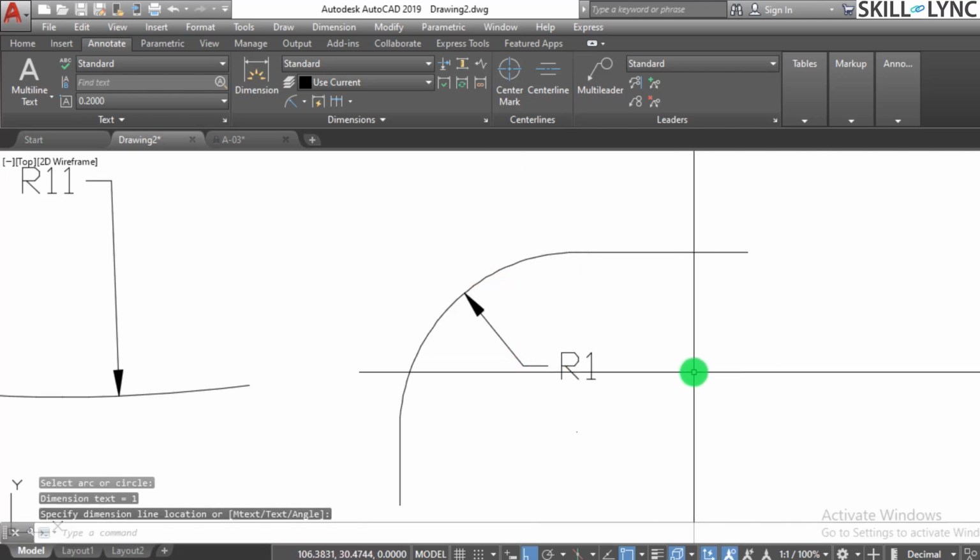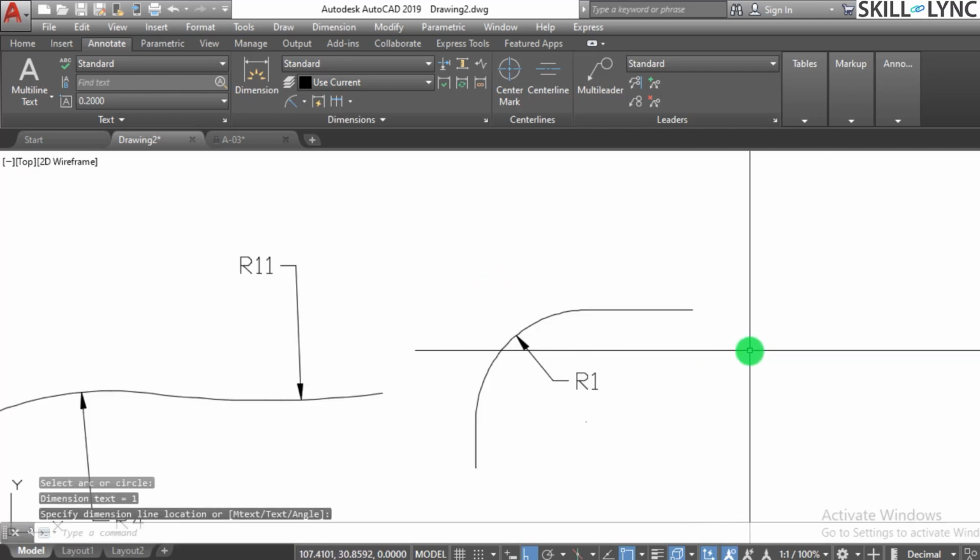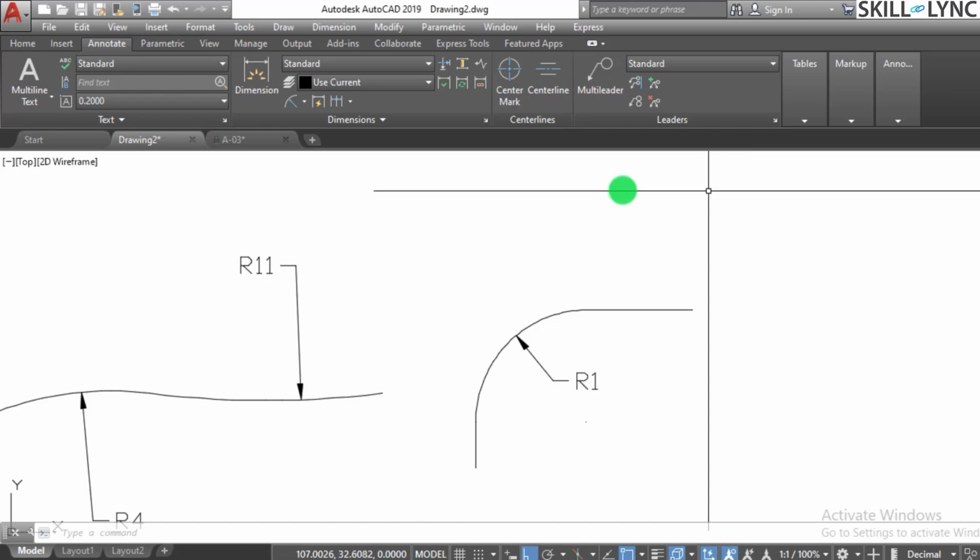So it is good that it has a radius of 1, so that with this information the workman can create the roundness in these edges, and they have measuring instruments by which they can measure. They have radius gauges or different kinds of surveying instruments to find out the curve radius of the particular surface or profile.